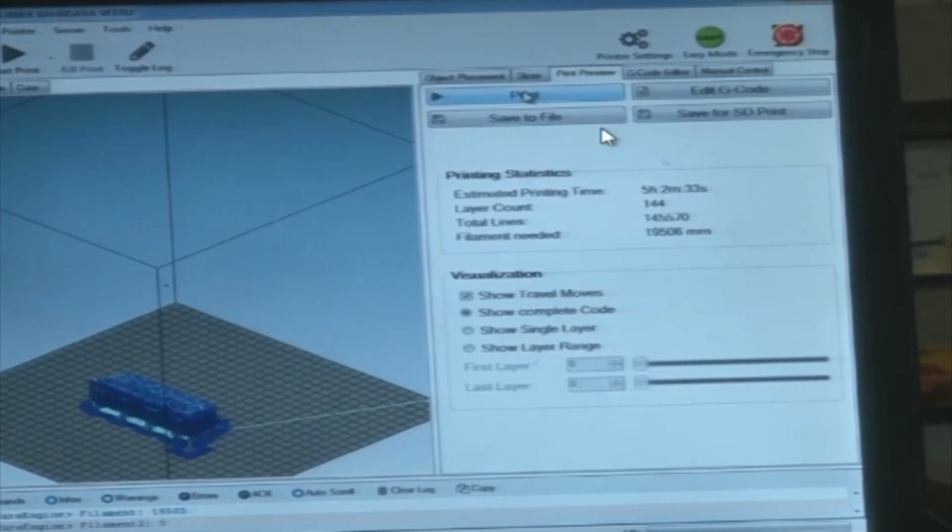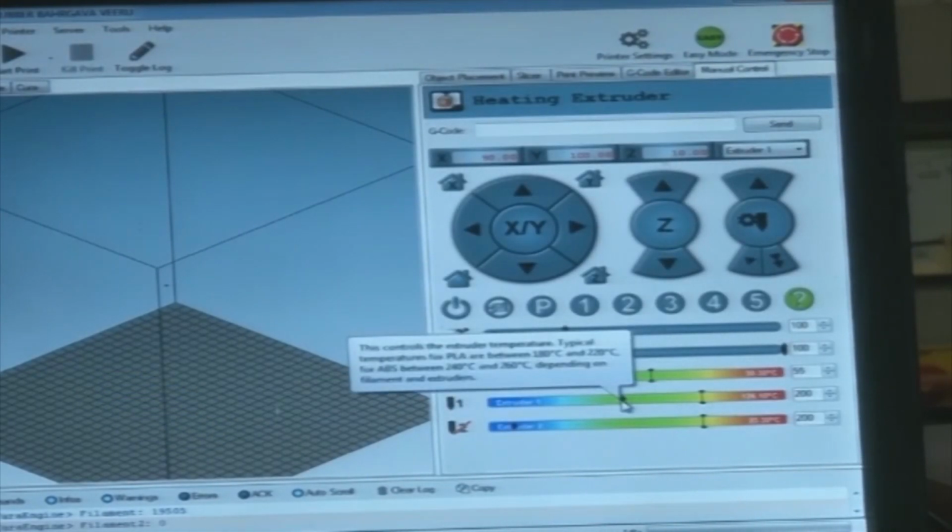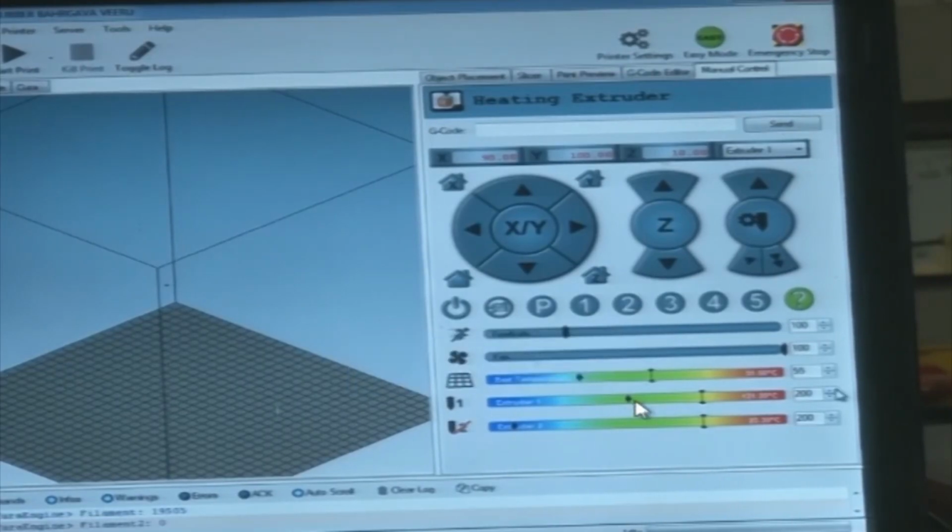Now there is another way. If we go to the print button here and click print, all these manual controls that we set manually will be enabled automatically, because the bed has to be heated, the nozzle has to be heated, and the fan has to be kept on. All the settings we made before would be activated by just clicking this button. So this is the automated mode. The use of manual control is that we can display and alter the temperatures, but in automated control we can't alter them once we fix them.